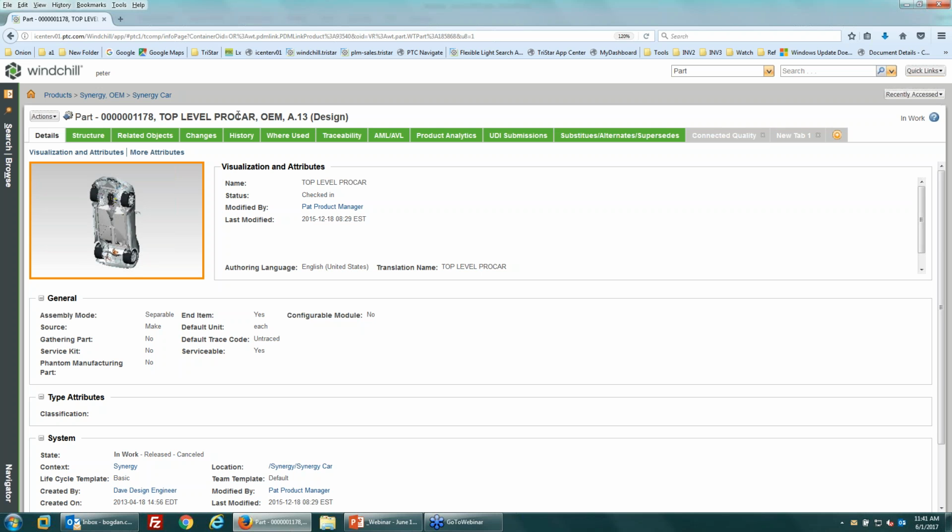So there may be modules or kits within that product that I can sell as a sellable item. It cannot be broken out into separate components. So I can designate some of these parts in Windchill as those end items. That differentiates just component parts versus what the top level part is. So it has a designation called an end item.